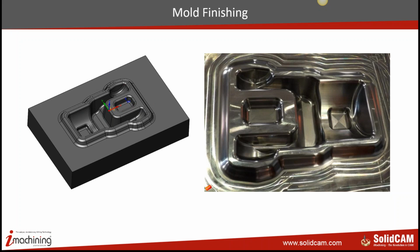Okay, it's not very easy. It's not easy at all to actually machine every surface along its flow lines. I remember, again, way back in the late 80s and early 90s, we had systems that were following it, and then CAM evolved. A lot of things became completely automated, and the concept of machining surfaces by their ISO lines or UV lines disappeared, and the entire surface model was triangulated, and then we started machining the triangulated model.